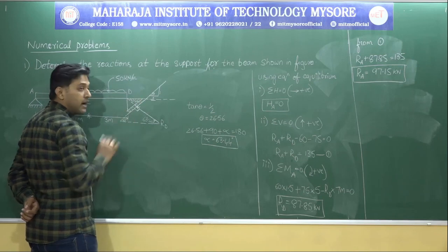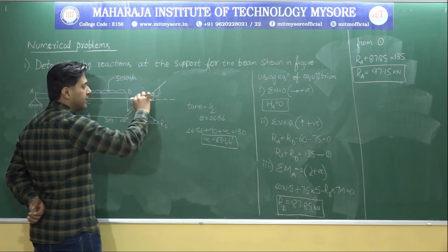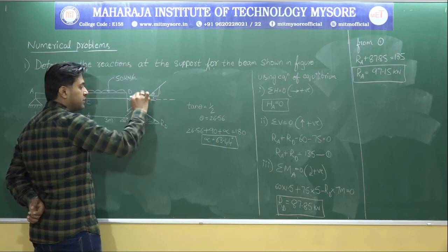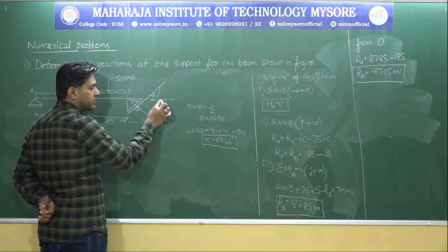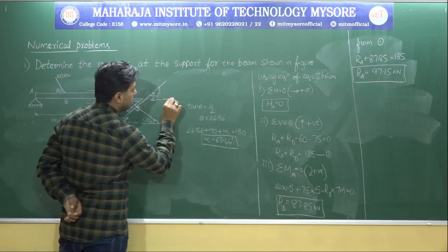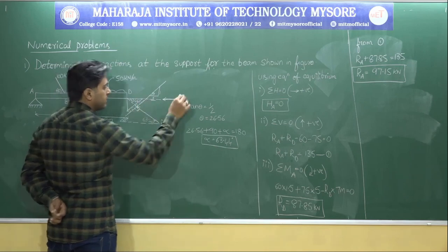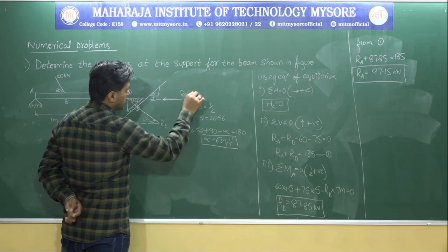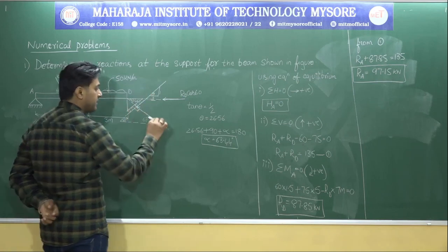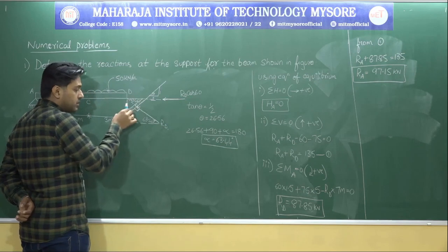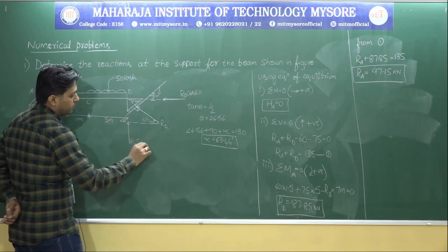63.44 degree. So now the inclined force is there. I know the angle. I want you people to tell me the force with which line it is inclined, or the force with which line it is making an angle. That will be cos, and the force is acting towards the point. Therefore its resolution should also act towards the point. So this will become RD cos 60. The inclined force with which line it is making an angle, that will be cos. The other one will be sine. Other one means the force is acting in an inclined manner. So this is the vertical force. So the vertical force is RD sine 60.